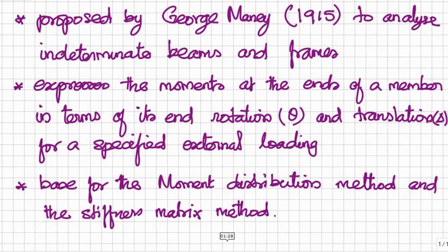In this method, we express the moments at the ends of a member in terms of its end rotations and translations, that is, slope and deflection, for a specified external loading. And this method is the base for the moment distribution method and stiffness matrix method.